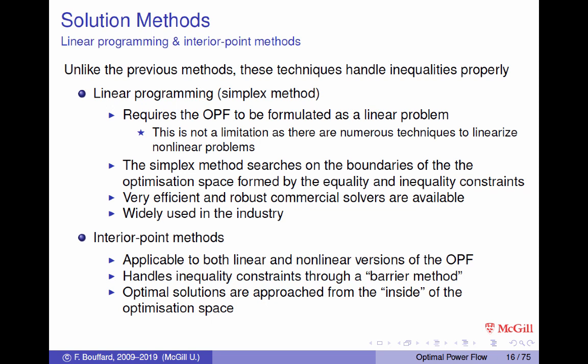Therefore, it has humongous practical implications. The downside is that we need to ditch the AC formulation and replace it with a DC formulation of the power flow equations. So clearly, we will lose some accuracy, but at least on the other end, we will gain solvability.